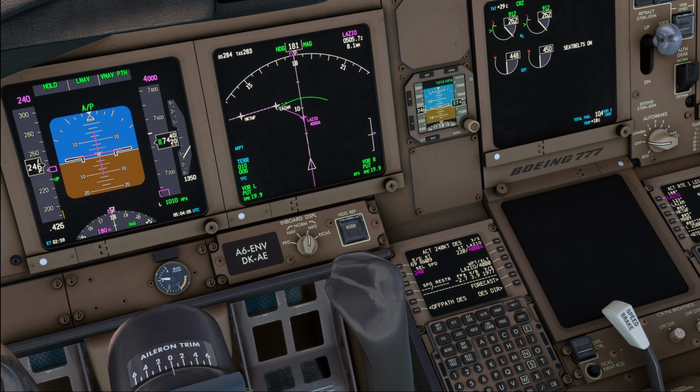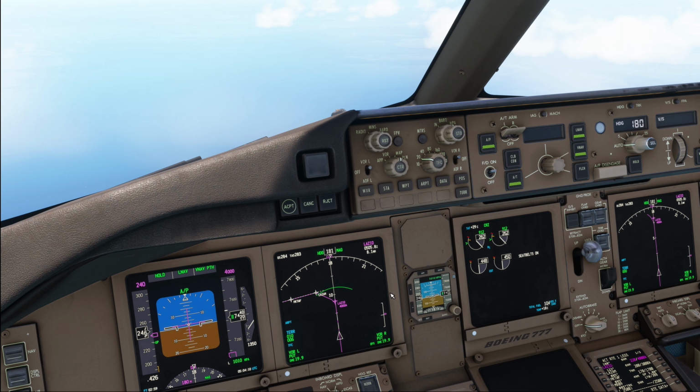Now, let's go ahead and have a look into a couple of basics. In order to be allowed to use LNAV for the approach, it is very much recommended that the approach is loaded from the nav database and not entered manually. Loading an approach from the database is required for any RNAV and GPS approaches, and if an approach procedure is selected through the FMC arrivals page, that simply provides the easiest and safest selection of waypoints, ensuring minimum margin for error. No waypoints may be added or deleted between the final approach fix and the missed approach point.